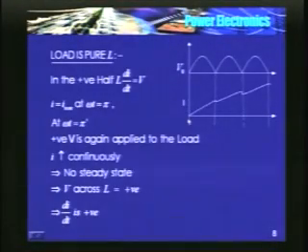What happens in the full wave rectification? Current starts from 0, sorry, it is not linear, okay, it increases and reaches a peak at omega t is equal to pi. Again at omega t is equal to pi plus, a positive voltage is appearing across the load. If the positive voltage appears across the load, it implies that di by dt has to be positive, because L di by dt is equal to V. So, left and right hand side is positive, so di by dt has to be positive.